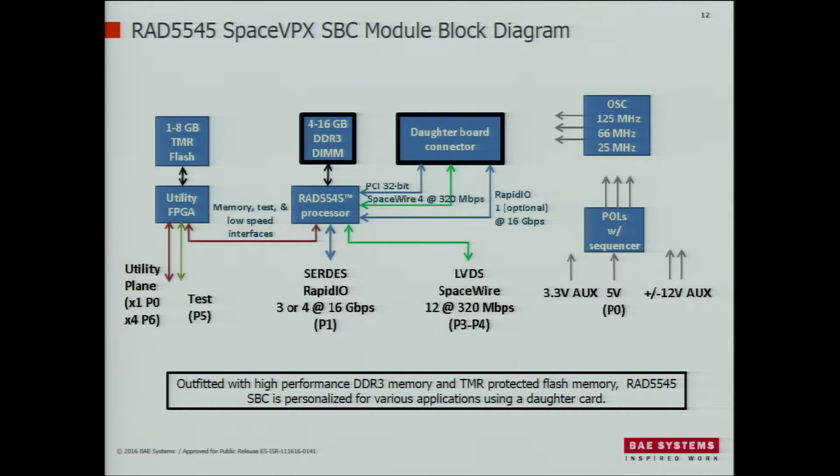The other thing with this card design is it's pretty flexible and modular. So for instance, the DDR3 memory is on a connector. So you can put in a commercial DDR XR-DIMM, or you can go to a more rugged space qualified DDR device to plug on here. And of course, the amount of memory you get can vary based on what you put on there.